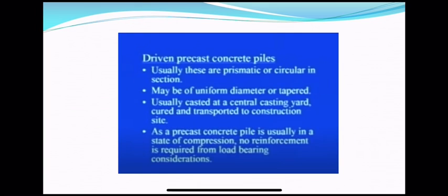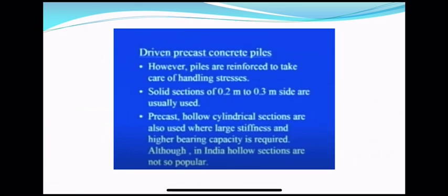Now, as the precast concrete pile is usually in a state of compression, no reinforcement is required from a load bearing consideration. So you simply cast it with concrete, it gets cured, transported, and then simply driven at the site. However, piles are reinforced to take care of handling stresses, although from the load bearing point of view you do not require any reinforcement. For handling stresses, you need to provide some reinforcement, in sections of 0.2 meters to 0.3 meters heights.